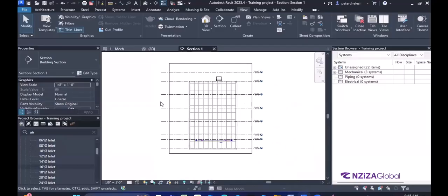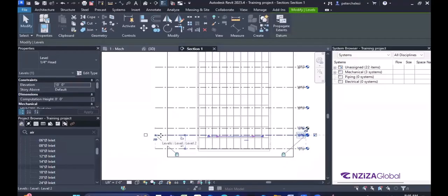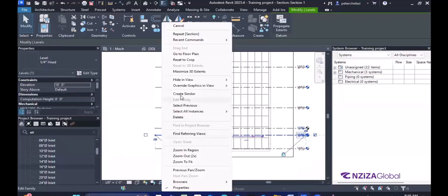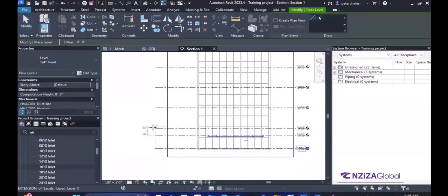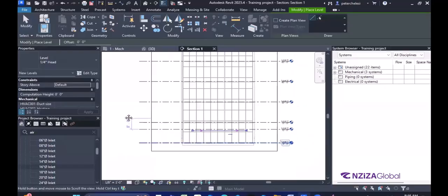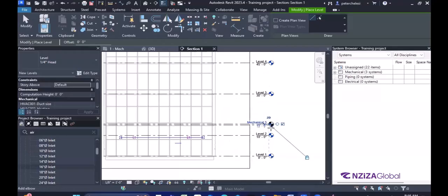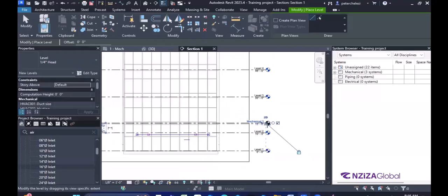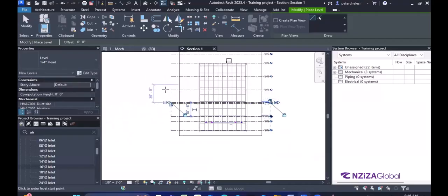If you want to go to another level, you just click level 1 or level 2. Just right click, then go to Create Similar. For that, let's create the multiple levels. So you can create maybe this one. This is to view level 3. We click another one, to view maybe level 4. We click another one.